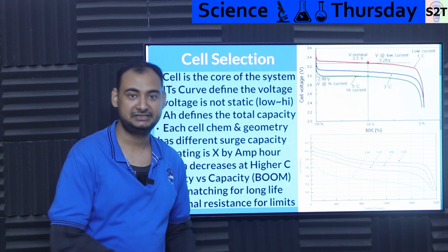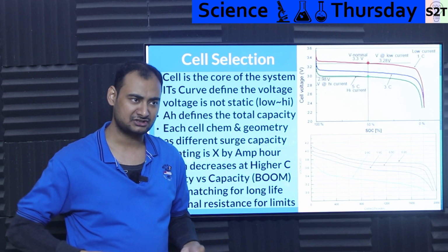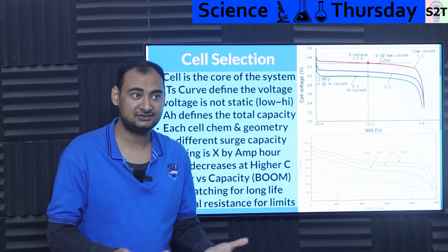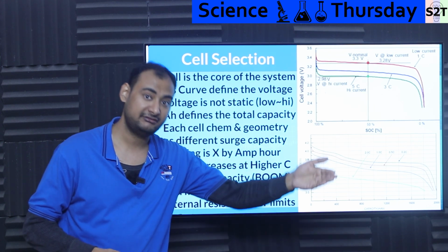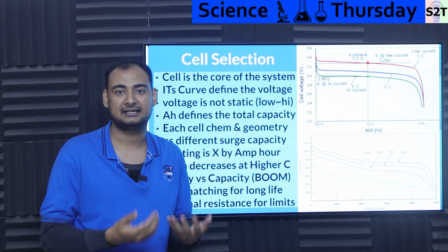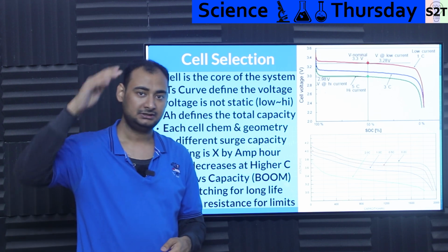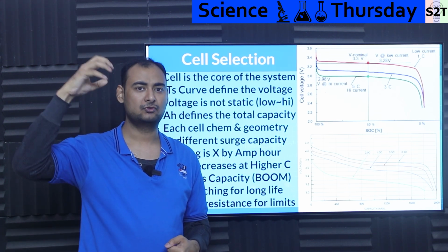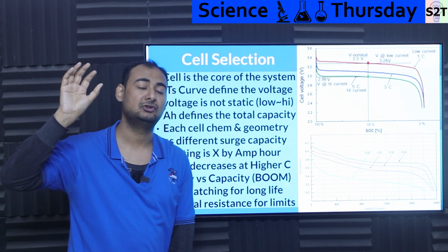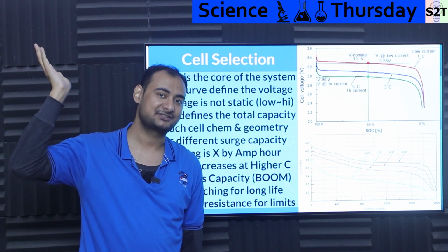Again, same thing goes with lithium ion chemistry. Any lithium ion chemistry that has a lot of capacity, fundamentally it catches on fire because it has so much energy. And as you go into safer chemistry, fundamentally the voltage goes down and you have less capacity. It has a higher safety factor. For example, nickel manganese cobalt has the most capacity, it's perfect for your mobile phone because even in small volume, you can have a lot of watt hour. Cool, awesome. It catches on fire.